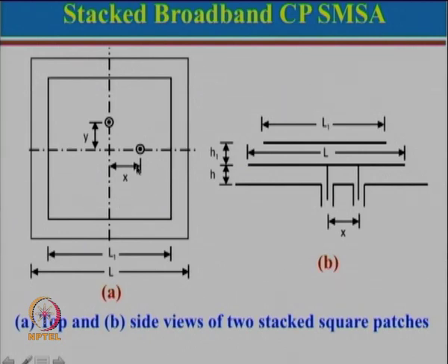but over here it has to be a square microstrip antenna, and here the configuration shown is that the bottom patch is fed at 2 orthogonal points, and then there is a top patch. Now, this configuration shown over here uses air here and air here, and of course, we need to practically support these antennas, and that can be supported right at the center over here.